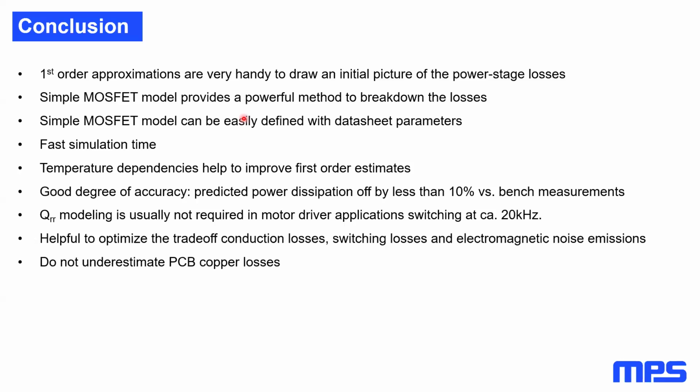We have quite a bit of experience, for example, with people dealing with motor drivers in the automotive body segment, where the EMC compliance, conducted EMC levels, as defined in the IEC standard, can be quite stringent, and the motor may be located some distance away. Some people may do this so-called mechatronic system. Everything is very compact. They can have a tendency to be more aggressive, switch faster, and reduce the power dissipation.